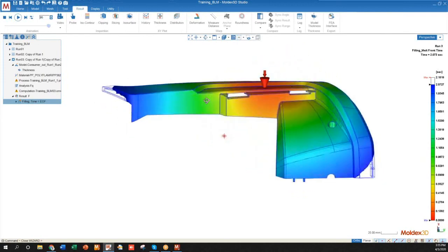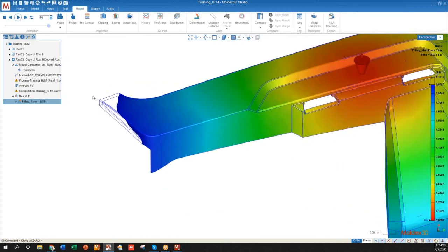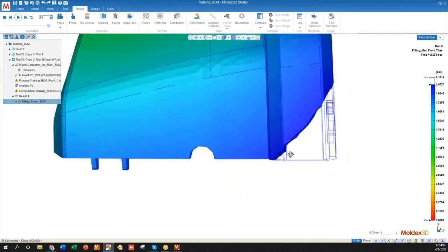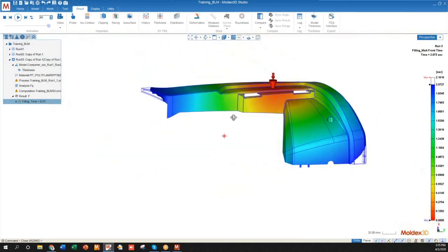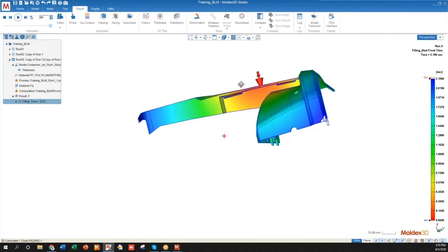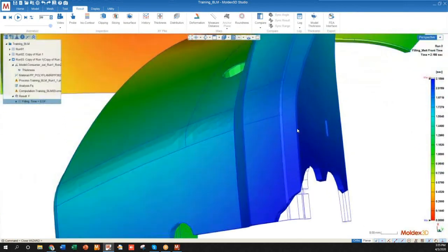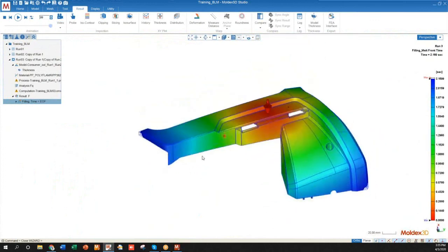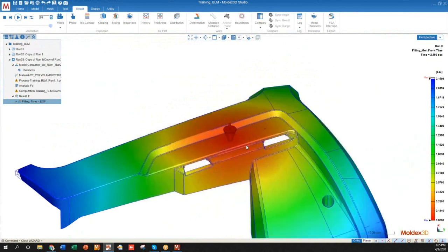And there you go. So we actually have, you can see both of my end of fill regions in this case are not finished filling yet. And like I mentioned previously, you can push this a little bit further if you want to see how balanced your fill is. You can see 97 is pretty well balanced still. Let's even push it to 99. All right, cool. Wow, we can still push it all the way to 99%. I can probably even push it a little bit further than that still. So this gate is actually very well balanced.